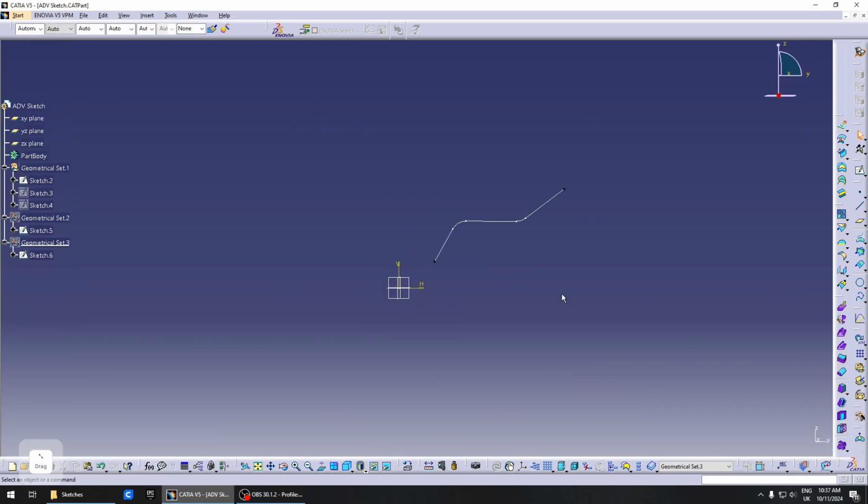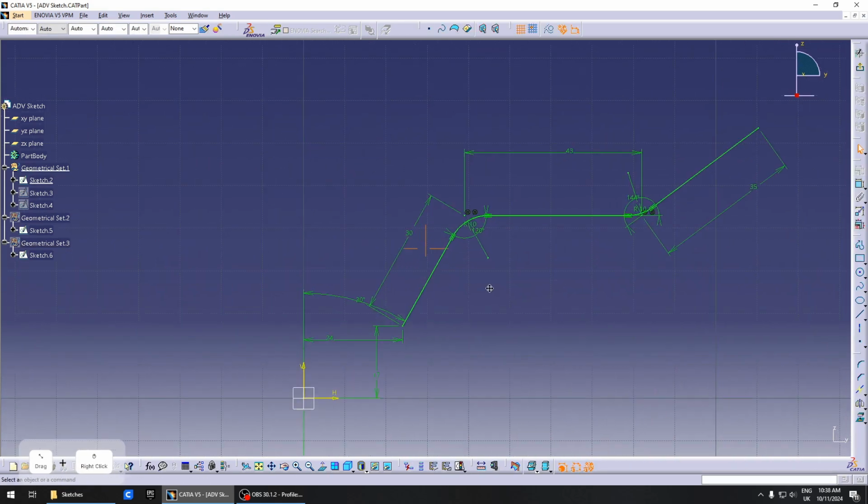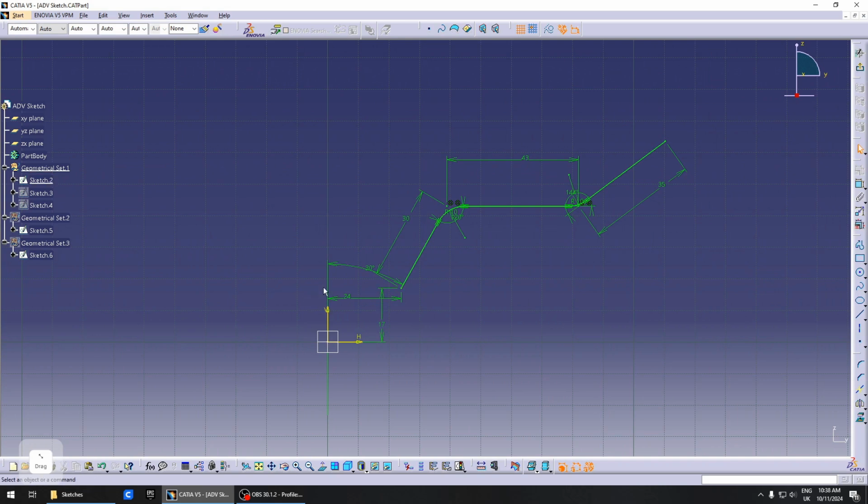Now that we know all about creating the sketches, we have to figure out what we actually put in them. So first things first, I would like to start with a simple tip, and it's mainly about when using constraints in a sketch. I've always said this, but try to use the reference plane as the reference axis as a base for your constraints.